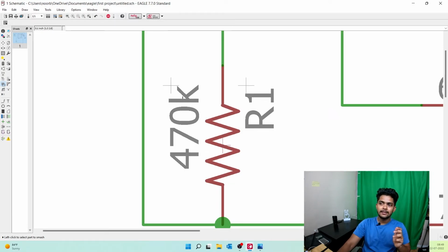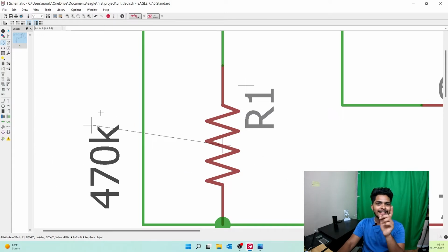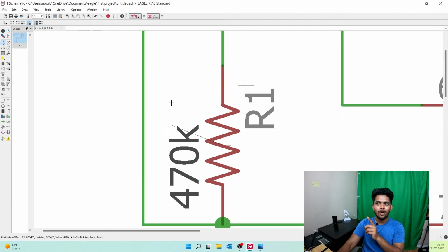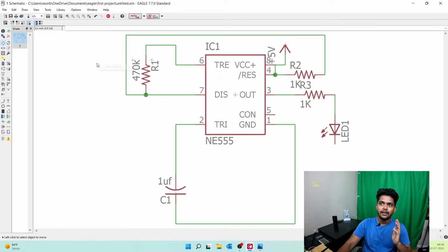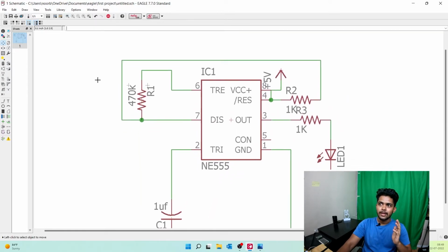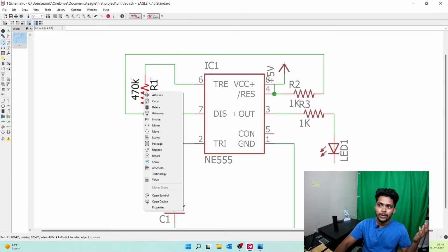Now, if I select a move tool and move this, it's already moving. And there is a black line, if you guys can see, over the component, which helps us guide where the component is located. Simple, right? Let me fit the screen again. Here, let me show you guys. See here, it is moving. Even if I keep it here and click on it, I know that that's related to that resistor. Simple. What we did, we selected the component, we went to smash.